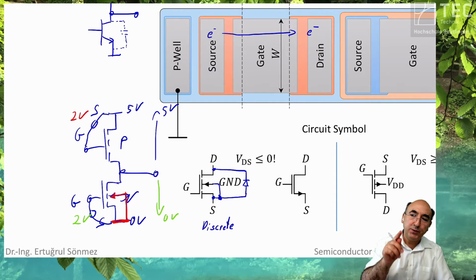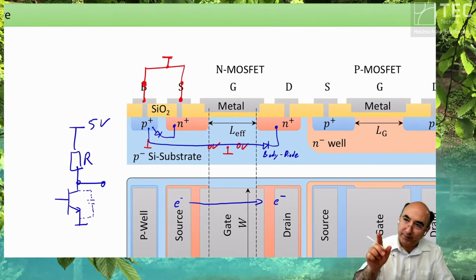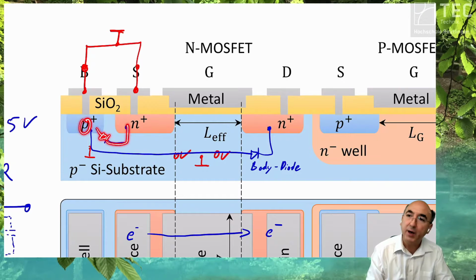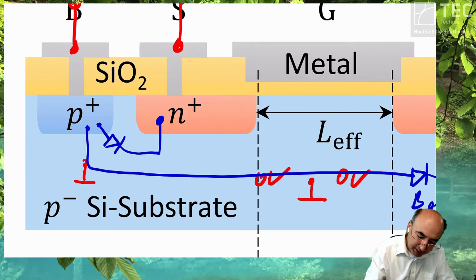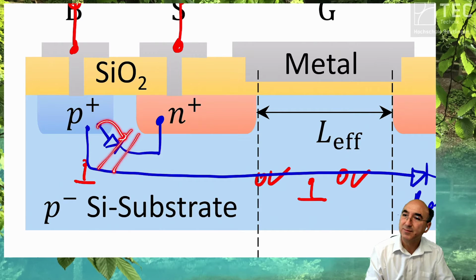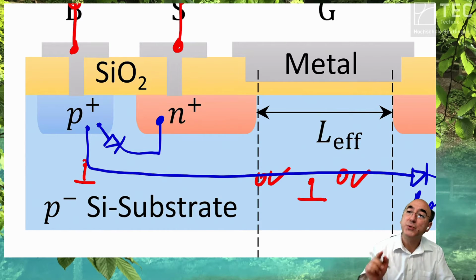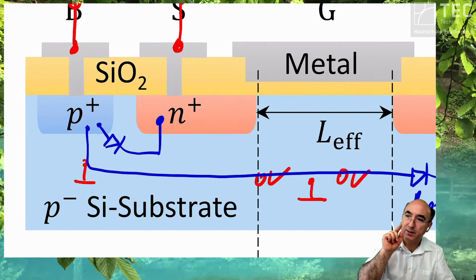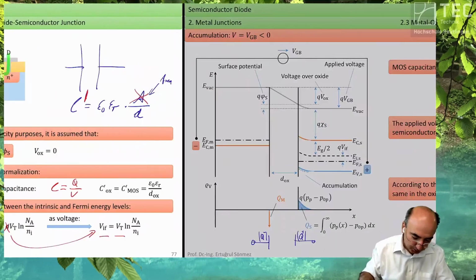And very often you don't want this diode because if this diode happens to have a forward current, we learned, then you inject holes into the space charge region and you inject electrons through the space charge region to the other side. Don't forget these conditions. Go back to the slide which I'm talking about at this moment.